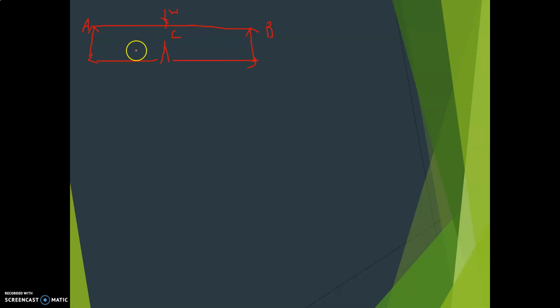So you have to find the shear force. Let us consider first the portion AC. Now this is section X, which is located at a distance of X from A. Now you can find the shear force at X. This is RA and this is RB. Shear force at X is the unbalanced vertical force to the left or right of the section. I consider the left section because X is close to support A.